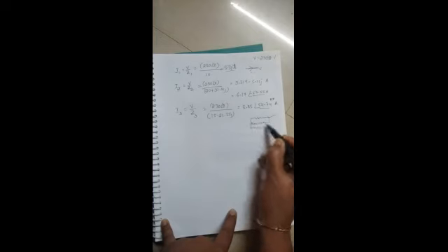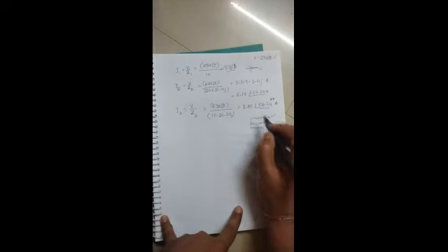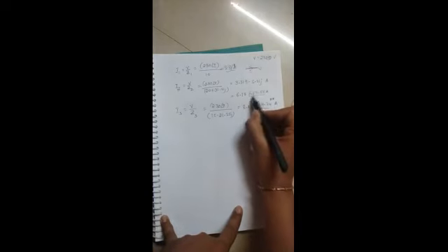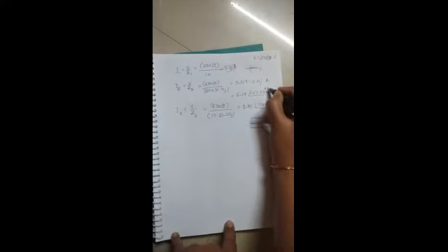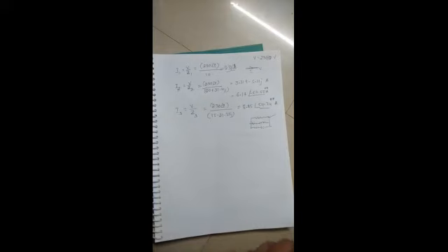I2 is the current flowing through the second branch, which consists of R and L. In an RL series circuit, current lags voltage by some angle phi. Similarly, the last branch carries the current I3, which you have calculated; observe its angle.